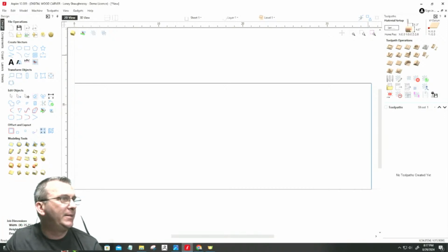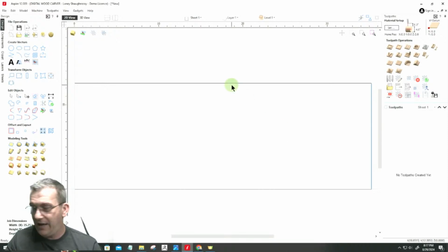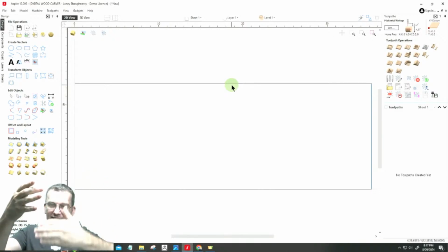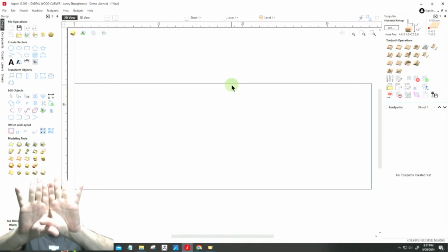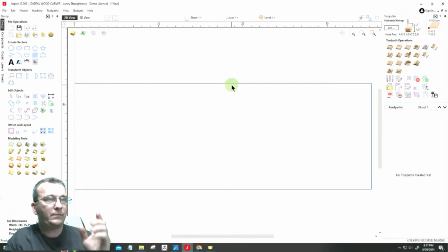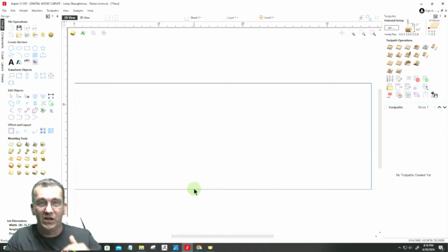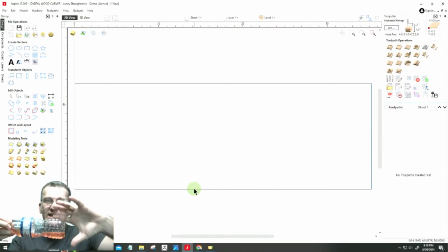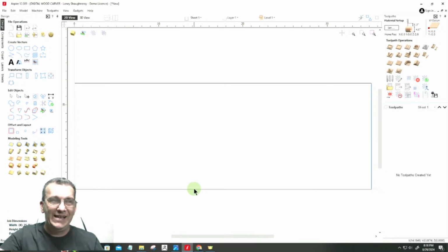All right, so we have here in this job setup, basically what you're looking at if you're new to rotary axis and rotary setup in Vectric is, think of a round paper towel roll, right? Think of taking a knife and slicing down that roll and then just unfolding it into a flat sheet. That's what we're looking at here. This is the circumference of that cylinder sliced and unwrapped into a flat plane. So on our screen, that's what we're looking at right here.